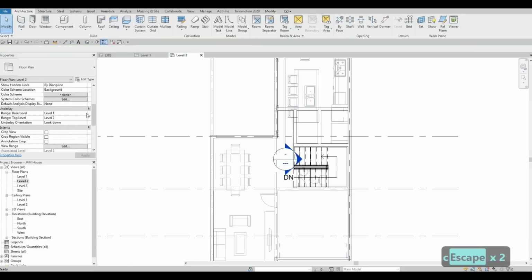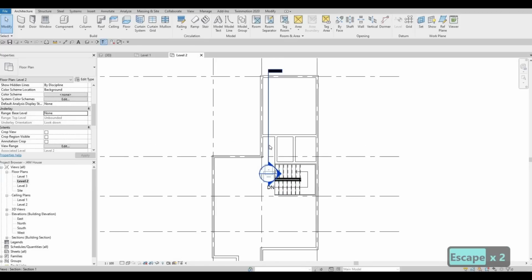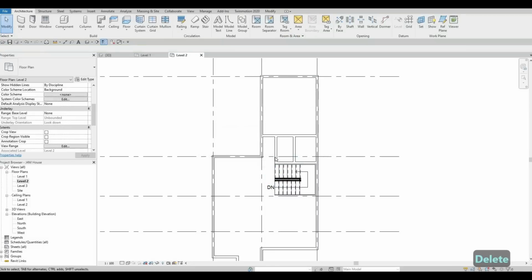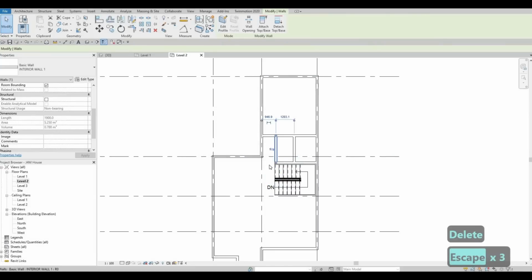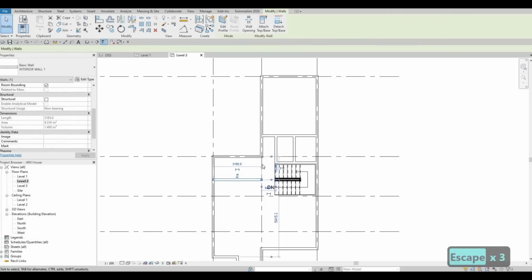So because this is probably confusing for you guys, I'm gonna turn on none for the underlay right before we could finish this. So here, this section, we could delete that for now. We don't need that. So here I'm gonna select interior wall again, CS, and then here we're going to add another 1500 from this one.